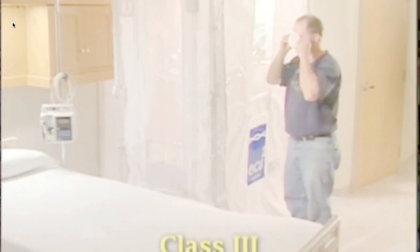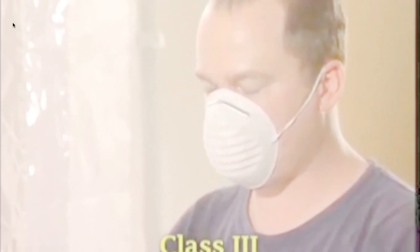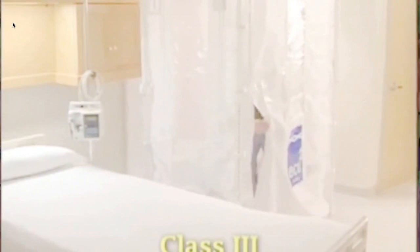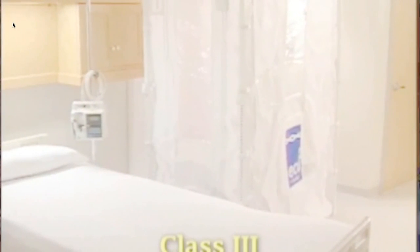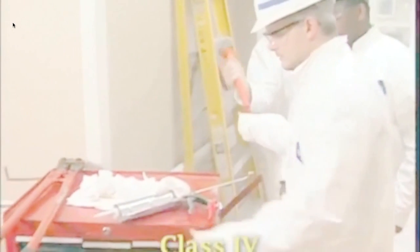Class 3 projects that generate moderate to high levels of dust require more intensive dust control measures. For example, barriers may be portable units or rigid walls that are sealed or caulked at the seams, and depending on official requirements may need to be fire rated. Holes, pipes, and conduits should also be sealed. Plastic sheeting may be used to seal off access to the work area while the barriers are being constructed and removed. Class 4 projects that are large and very dusty combine all the previous activities and add maximum infection control barriers to prevent dust or dirt from escaping the area.